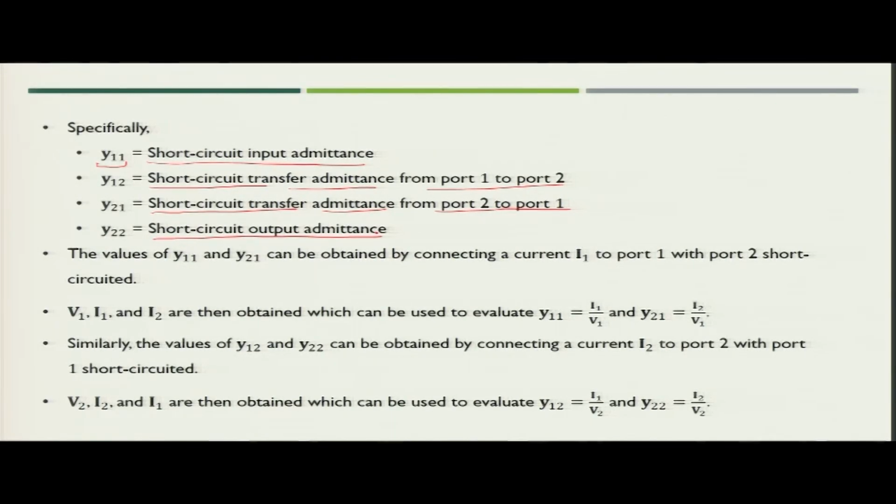As we discussed in the previous slide, the values of Y11 and Y21 can be obtained by connecting a current source to port 1 with port 2 short circuited.